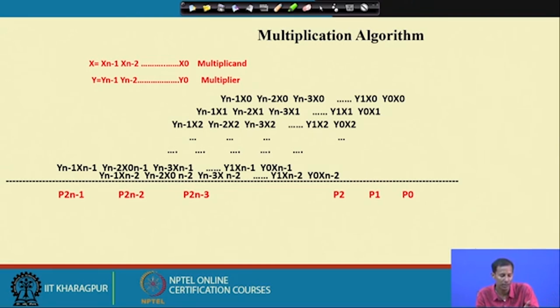So, initially there were 4 bits for x, now I am shifting that by an additional 3 bits, left shift. So, now the length becomes 7, and where will the other bit come from? As I am doing this bitwise addition operation for finding the final products, at the final stage there will be the carry out.